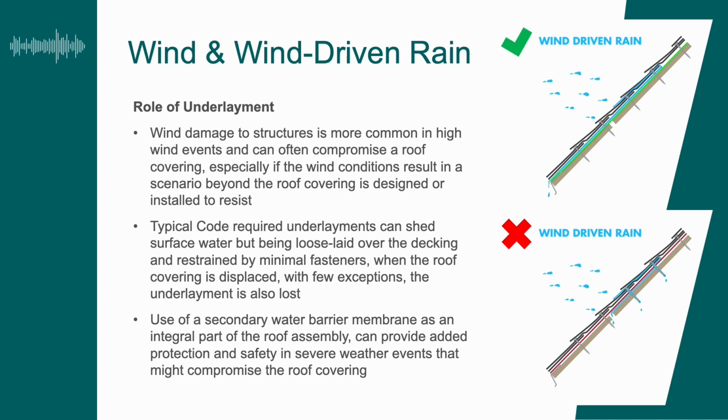Depending on the design, concrete tile and battens tend to hold a fair amount of water, so it takes a while for it to migrate off, and if the underlayment isn't a sufficient type or installed well, you're going to have problems, with water migrating down through the fasteners holding various things down. A secondary water barrier has various elements of fastener sealability as you're penetrating through, so you don't get that same condition of water migrating into the structure itself.